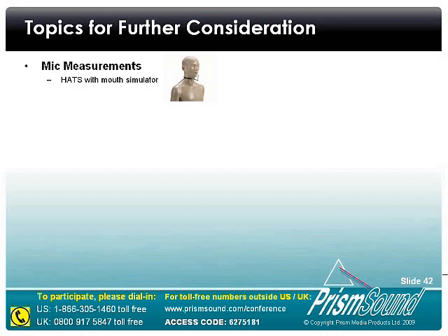For example, we would potentially need to equalize the generator stimulus to compensate for the frequency response of the mouth simulator. Hence, you can see in this diagram there's a reference mic attached to the front of this head and torso simulator here to allow us to make a measurement and then calibrate or correct, equalize for that response.